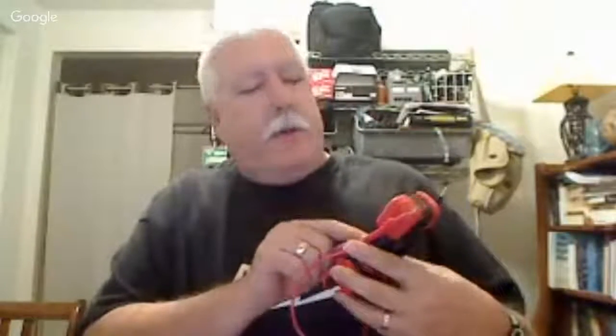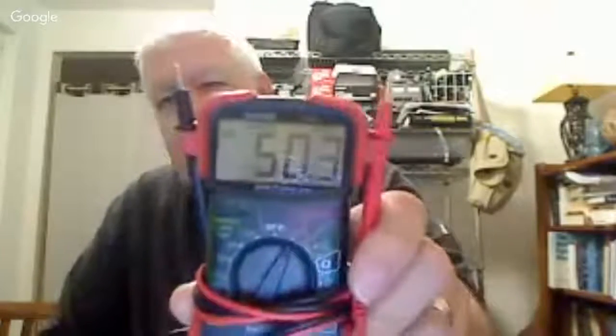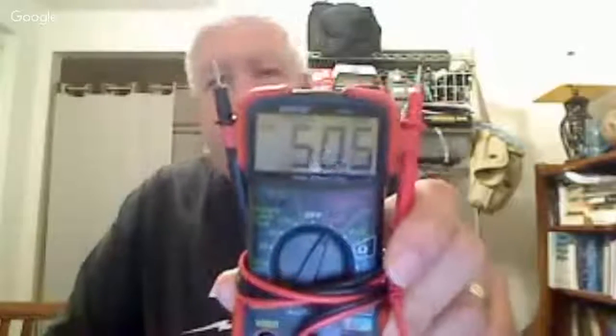T7D01, which instrument would you use to measure electric potential or electromotive force? Well, a voltmeter is what you use. Come in all kinds of shapes and sizes. Here is a voltmeter that also does some other things. It does other readings as well. But you set it on voltage, and you have to select AC or DC in this case, and there you are. Voltage is measured in parallel with the circuit. So, and we'll talk about that a little bit more. Okay, voltmeter.